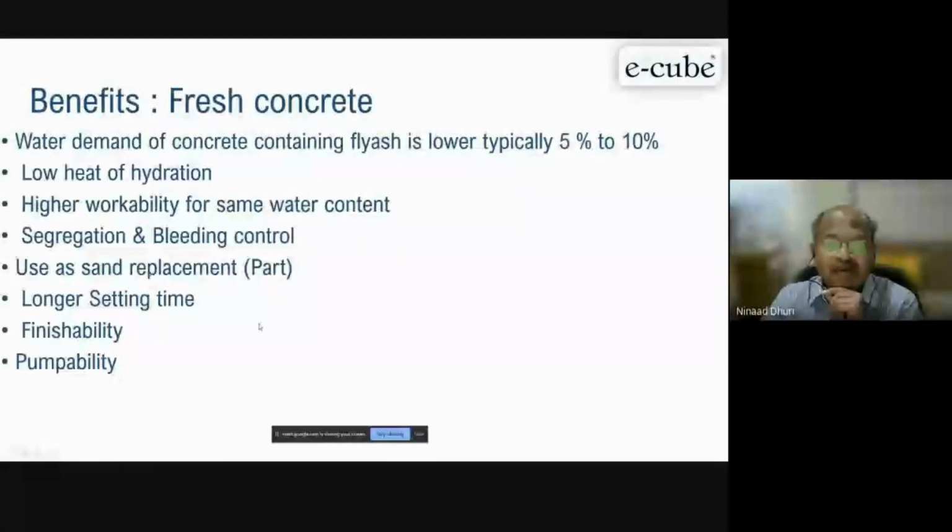So what we are advising is, whenever you are doing any foundation of a building, where the load may come on the foundation after 1 year or 2 years, you better go with fly ash concrete and optimize your economical mix and take advantage of that later strength.